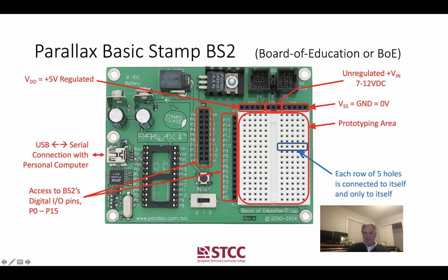There are power supply pins arranged up here, and there's a general purpose prototyping board, or breadboard, if you like to call it that, in this white area. And just to remind you, you may have burned this into your memory by now, but just in case, the way these breadboards work, each group of 5 holes is connected. So if you plug anything into any of these 5 holes, it's connected with conducting metal underneath. So that's the way you build circuits.